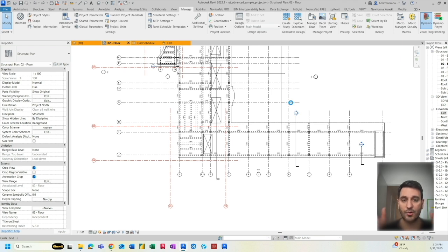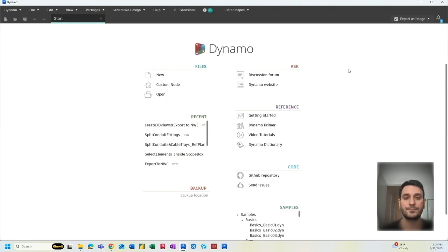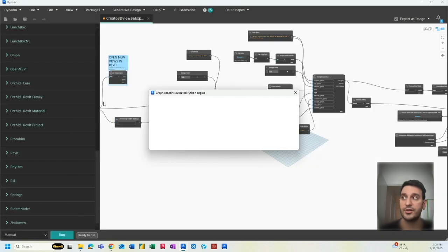We name them, and once we load them from an Excel file, we can connect our Dynamo to that Excel and then start creating the views. Okay, so let's review this script together. I'm not going to write it again for you, and I'm going to share this script if anyone requires that.